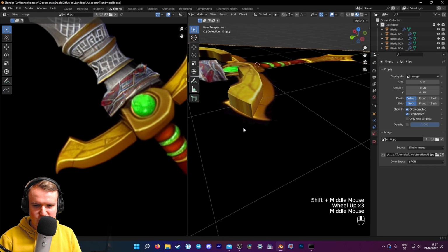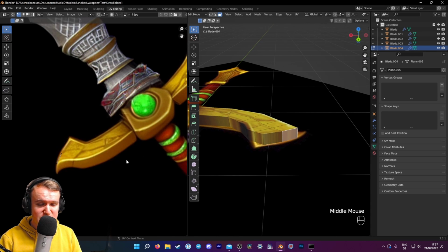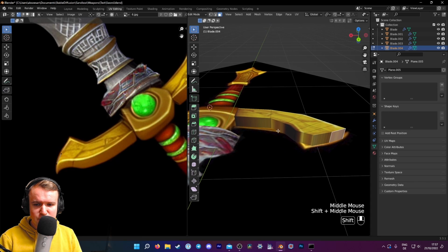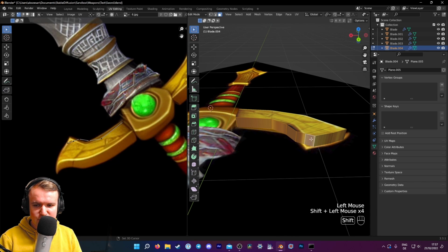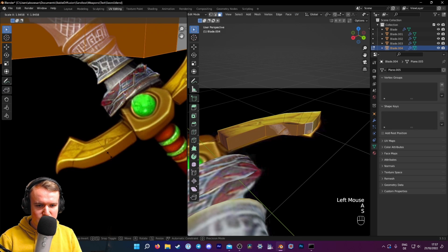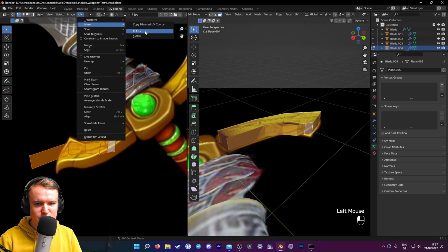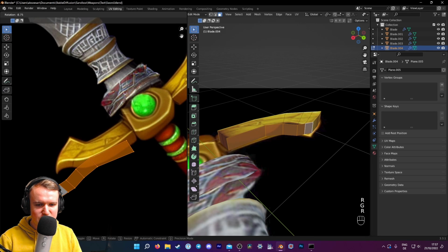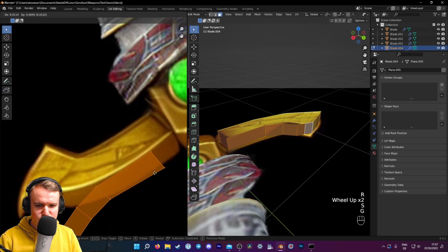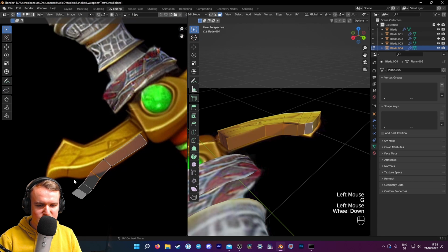So this is where it gets a little complicated. Obviously, we don't have any sort of information on what this side looks like in our 2D image because it's just not there. So the way I do that is I improvise a little bit, right? So I'm still going to UV project and bring that down here. But I'm going to mirror this, right? So I assume the top looks quite similar to the bottom, so why not just do the same exact thing? So I just put it here, make sure the vertices are roughly where I want them to be.